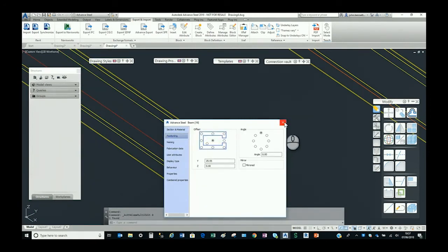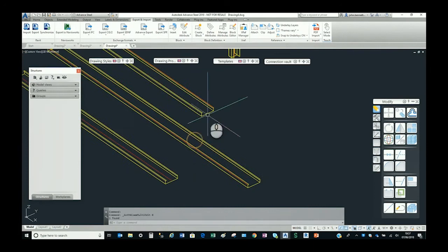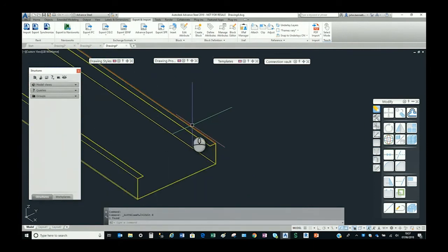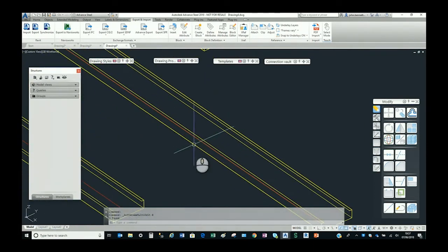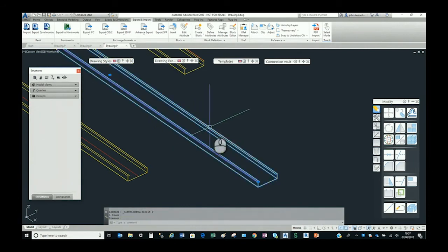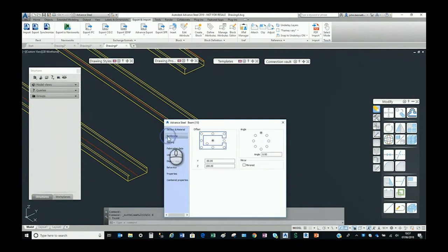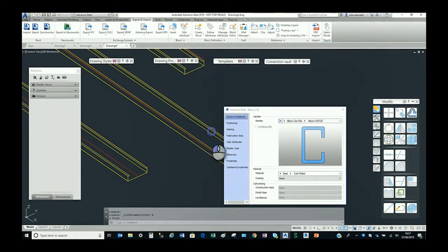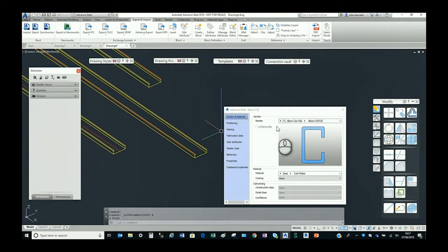So at least the guy doing the detailing would probably have a better start point. Wouldn't have to worry about the orientation of the objects, etc. There are a few funnies there. There's a few offsets in there that we normally wouldn't apply in Advanced Steel. We'd normally teach people not to do that. But in this case, it does put the system line where it needs to be.